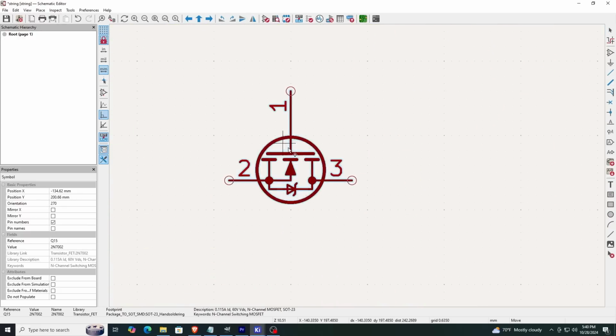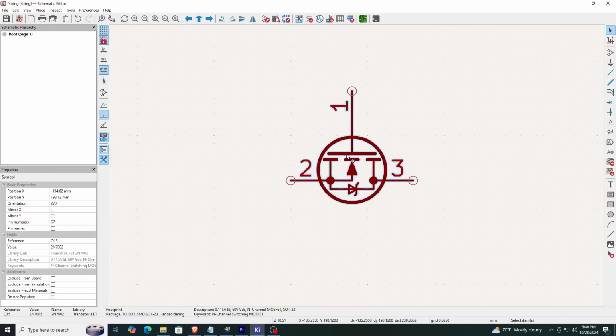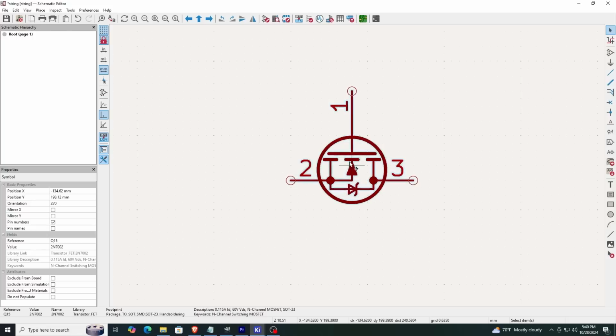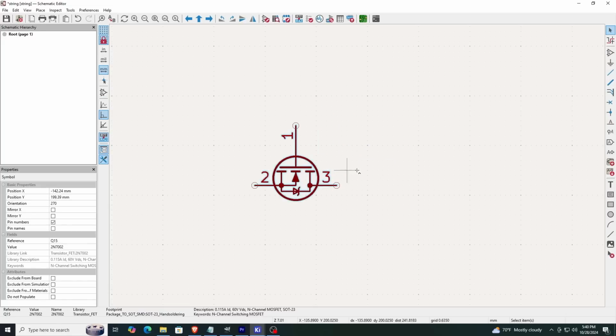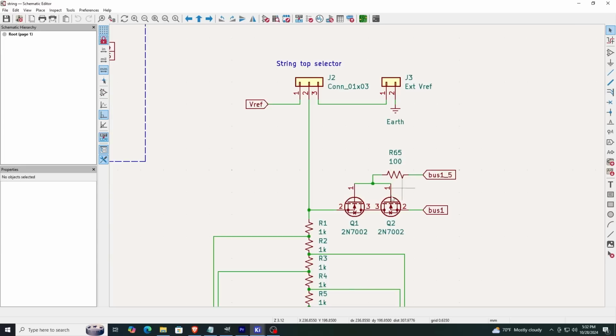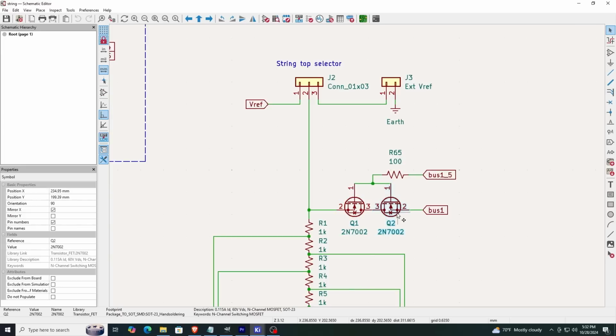Now, for the switches. I wanted to use discrete MOSFETs at first, since they would make for good analog switches. But I quickly remembered that discrete MOSFETs don't come with a connection to the substrate. Instead, it is connected to the source internally, which creates this body diode you always see on the diagrams. This diode is undesirable to our situation. To fix the problem, you could put 2 transistors back to back in order to null out the effect of the diodes. This creates a new problem though, in that it doubles the number of transistors that would be needed. I did end up using this method for the high switch, but for all the others I found a different solution.